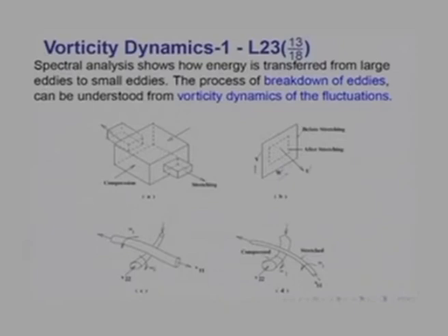Then, if the turbulence is very high in the large eddies, where viscosity would have very little influence, you will see that the plane of cross section must shrink, as I have shown here, because of the stretching in the x direction. The cross section in the y and z directions, or the length scales associated with them, must decrease.